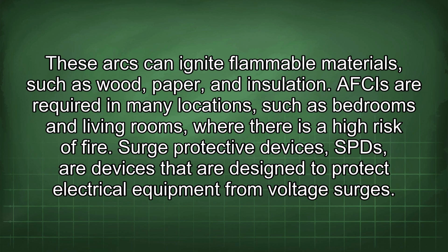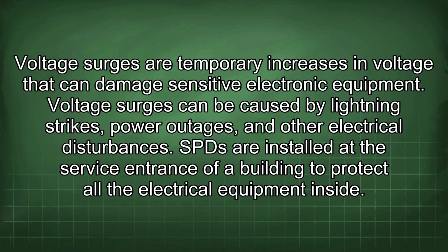Surge protective devices, SPDs, are devices that are designed to protect electrical equipment from voltage surges. Voltage surges are temporary increases in voltage that can damage sensitive electronic equipment. Voltage surges can be caused by lightning strikes, power outages, and other electrical disturbances. SPDs are installed at the service entrance of a building to protect all the electrical equipment inside.